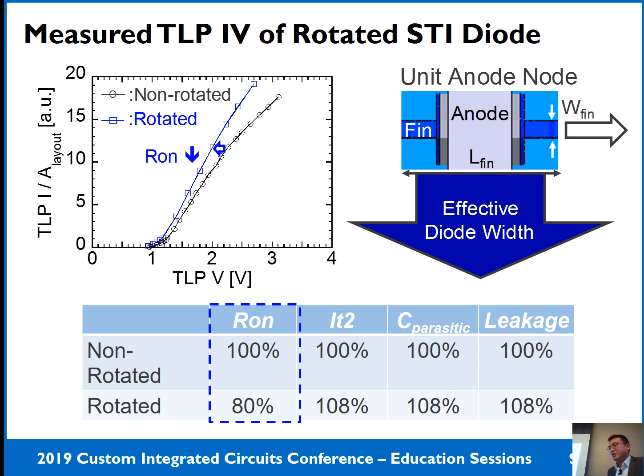So if your package becomes bigger, at the same charge voltage your peak current will become higher or even larger. So this is an issue. I think in the standard meeting they really discussed lowering this requirement level in the future, but not only because of the technology, but also because of all this stacking and packaging. Many systems will be integrated in the same die or package. This will be an issue.